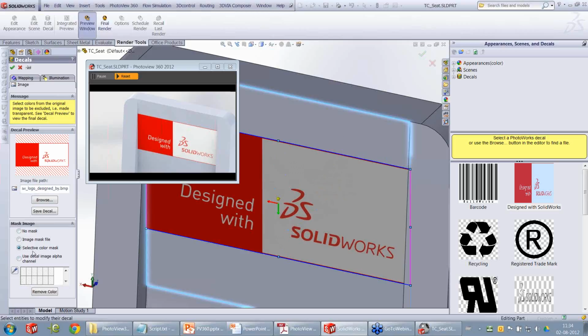So we can use the selective color mask option. Just click on this pick color button, and go back to your decal preview, not the graphics area, but the decal preview. You can choose any particular color, and SolidWorks will get rid of this color. You can see that in the preview itself it's updated, in the model also it's updated. So basically you have selected one particular color, which is white. SolidWorks is getting rid of that color.